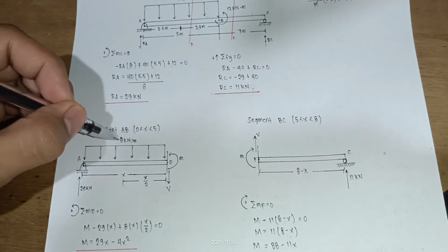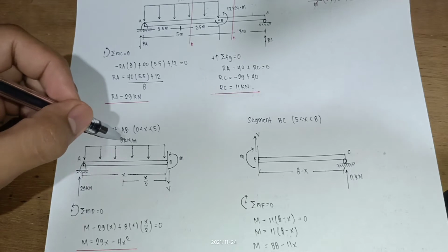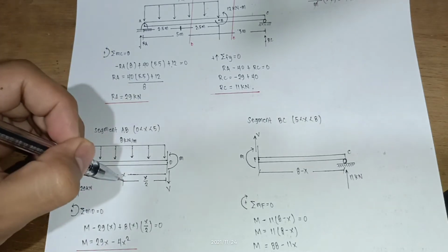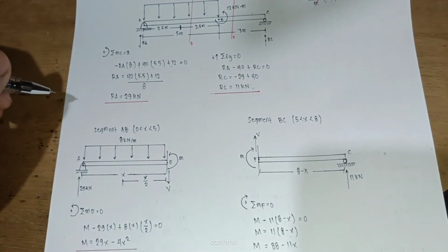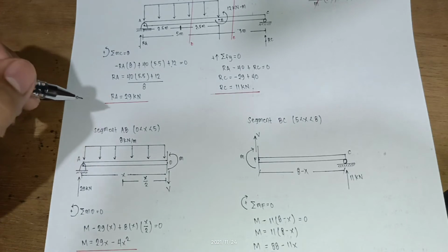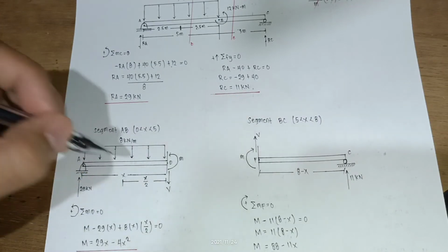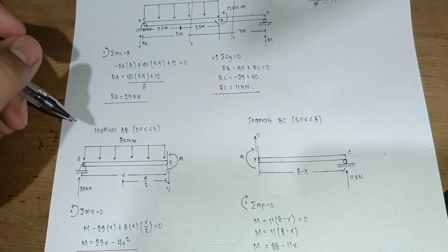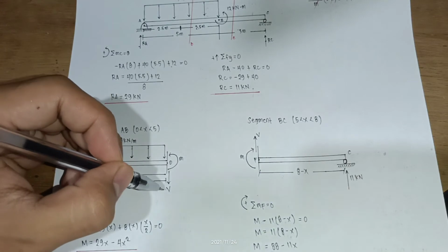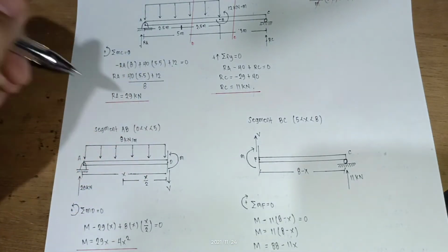Then we have a distributed load of 8 kilonewton per meter, so the middle distance will be divided by 1/2. So x times 1/2, it will be x over 2. Then the shear force V is downward, that is positive, and a moment